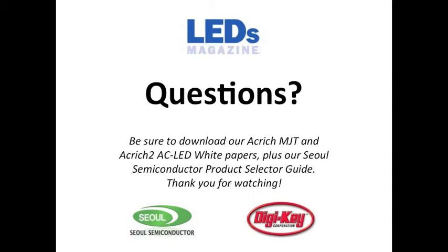So there are a bunch of different ways to put multiple die in a package. And that's the difference, if I understand you correctly, that some people actually take separate die and run wire bonds along the top of the chip. Correct. Now, are your die already singulated when you put them down on this metallized substrate, or is it actually developed that way? It's actually developed that way, so you grow them as multiple die. So it's not setting multiple chips down on a package.